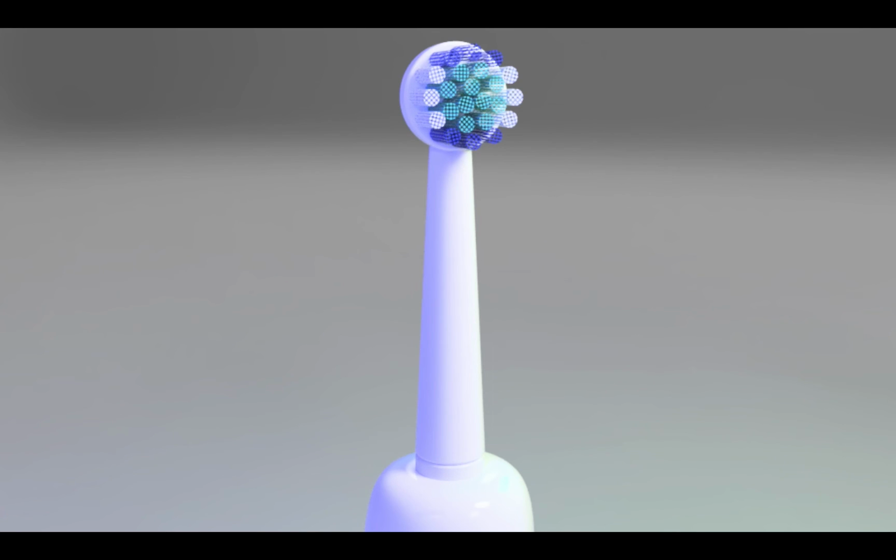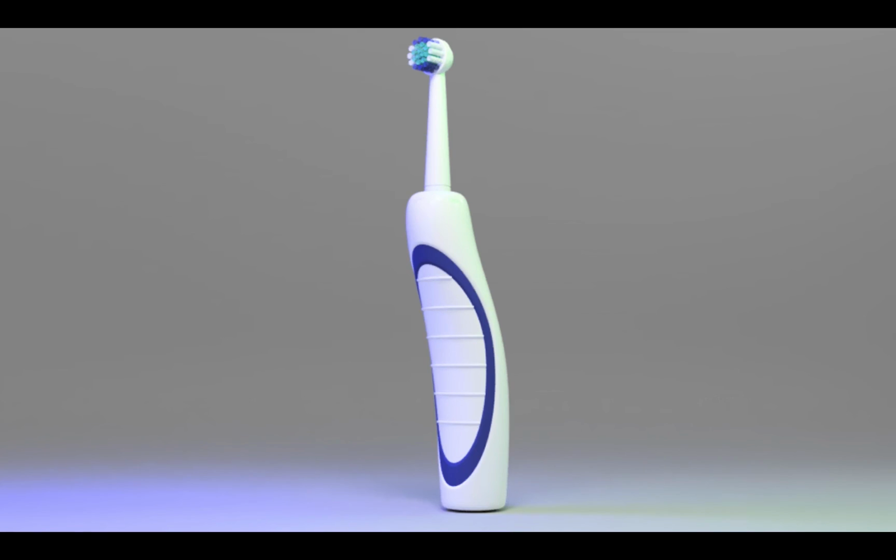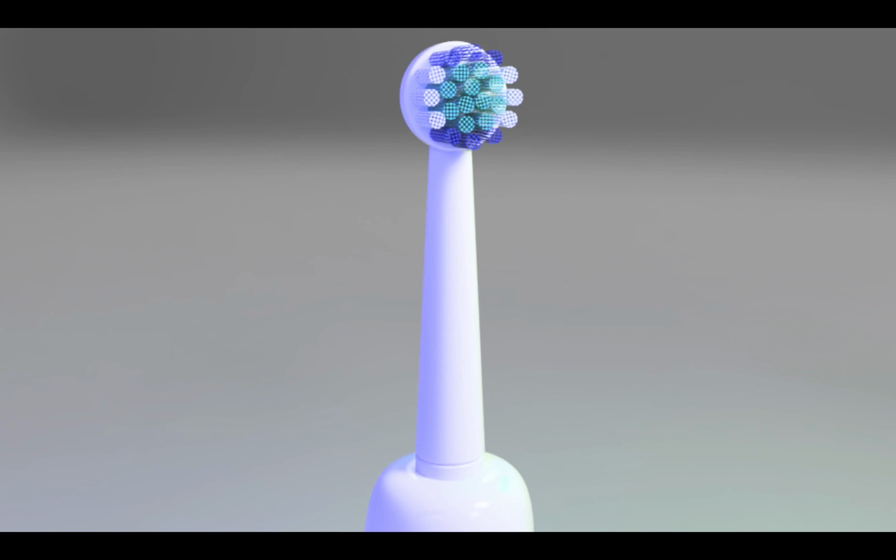You can see in the bristles I cheated a little bit. Instead of modeling each bristle, I just did a cylinder to represent a bundle of bristles, and then I used some of the material options in the appearance library, and I added some cutout patterns. So I used a polka dot pattern to create the little dots for the end of the bristles and a line pattern to create the horizontal lines. And so zoomed in, you can see I cheated, but in a rendering, or maybe not cheated, but I'm just trying to be quick and efficient in my modeling.